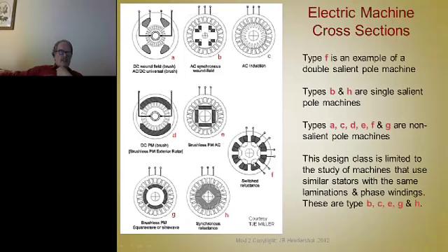So in reluctance machines, the torque and performance you get is based upon how well you can create this saliency, or how big a difference you can design into the geometry such that one inductance is a lot higher than the other one.